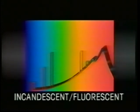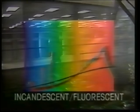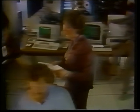Under this system, a fluorescent lamp designated as 3000 degrees CCT will approximate the appearance of an incandescent lamp designated as 3000 degrees Kelvin. If measured by instruments, one could see that they were not, in fact, the same. But the correlated color temperature is based on the sensitivity of the human eye and the effort of the brain to perceive nearly white sources as white. Correlated color temperature gives you the ability to describe a fluorescent lamp in terms of warm or cool appearance. However, it does not define how a lamp will make colors appear.